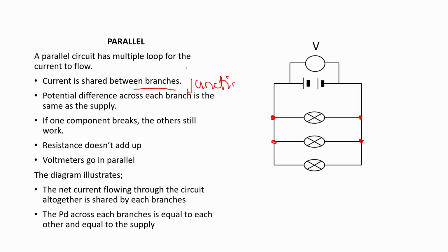And therefore, when we're talking about current being shared, what we really mean is it splits, because again, we have to be careful they don't think shared means it's shared equally, because again it depends on what we've got. So for example, if I've got something like, say, 6 amps coming up to this junction here and 2 amps goes in this direction, then I must have 4 amps going in this direction.